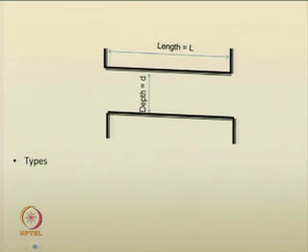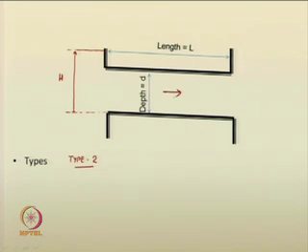In the second condition, same thing. So, if I give it as type 2, what is type 2 flow? In type 2 flow, this is your headwater depth, the depth of the culvert is given, flow is occurring in this direction, and inside the culvert it is almost full.